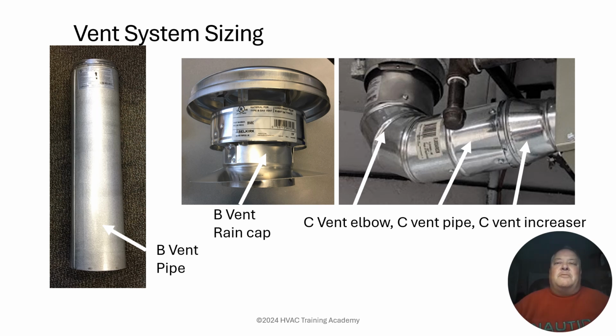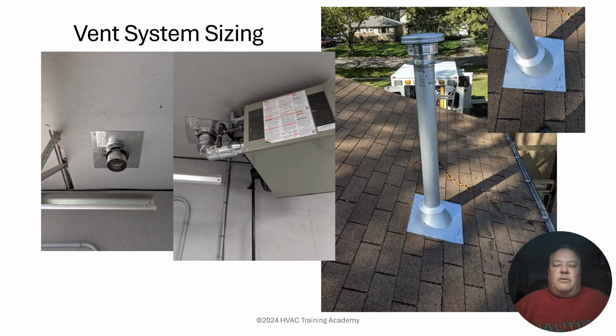So you can see on this garage heater that I put in, we've got a 3-inch outlet off the garage heater, but we quickly moved to a 4-inch, and the actual B vent system is 4-inch all the way up through the roof itself. And you can see again, before the venting is hooked up, I basically took a picture of the actual base support with the B vent attached to it, holding it up into the ceiling. And then you can see after I put the heater up, the actual piping and everything attached to that, the venting itself.